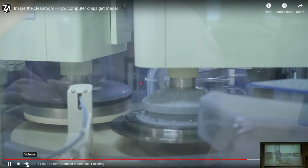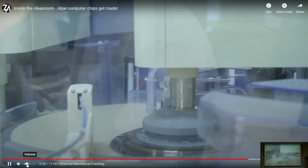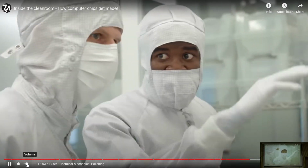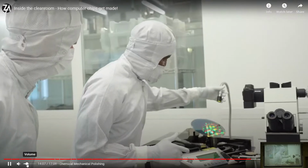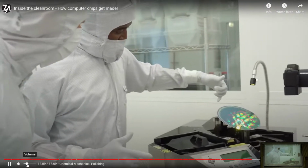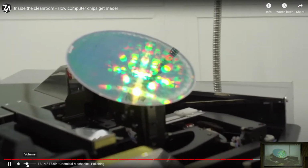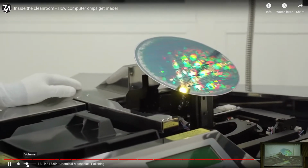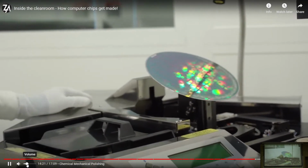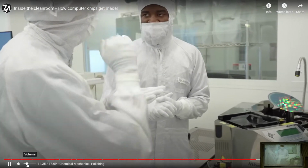And then this is coming to dress the wheel again to clean it. Exactly. So after using the tungsten CMP, I have to check if there's tungsten residue on it. For this particular process right now, you can see some white cloudy stuff on it here. So there's tungsten on it. You can see there's a little tungsten on it. So I have to see what to do to make sure everything is clean. Needs to go back in the machine. Yeah, probably for longer. So you're aiming between not enough and too much, and you've got to get it just perfect.